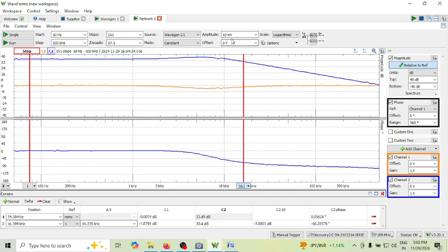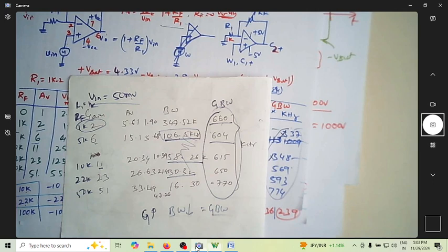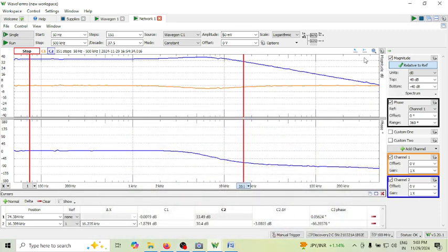You can see I have kept it as, so this was 10 millivolt, which is okay. It was not actually 50, it is even lesser. Even if I keep 50 millivolt, that is fine. All these readings that I've taken are for 50 millivolt, which will cater for all gains. So while doing the experiment, especially the frequency response, keep the amplitude small so that you'll have a larger bandwidth. You can experiment it out.